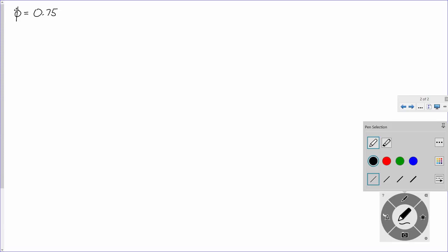All right, now we're trying to calculate phi Vn, right? So phi Vn is our goal. So how do we calculate Vn? This is really going to be plug and chug. What does the manual say on the second page, page 154? How do we calculate Vn? Vc plus Vs. Now, how do we calculate Vc?